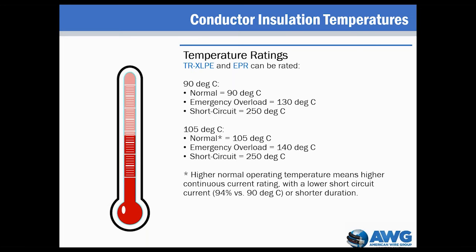Since TRXLPE and EPR are both thermoset insulation systems, the maximum temperature ratings can be the same. 105 degrees Celsius has been the typical normal conductor operating temperature rating for EPR insulated power cable, while it's becoming more typical for TRXLPE insulated medium voltage power cable.